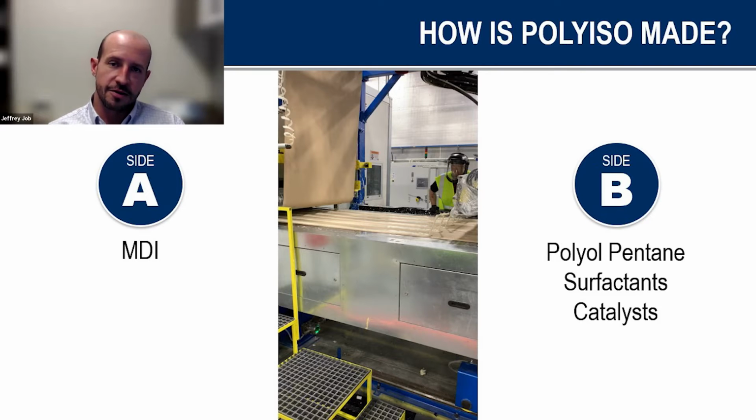Anybody in the roofing industry understands when we're talking about securement methods, adhesive is typically quite a bit more expensive than your traditional fasteners. So if we're spending extra money and going with an adhered system, switching to a CGF facer can help extend your coverage rate and really maximize the use of that adhesive.